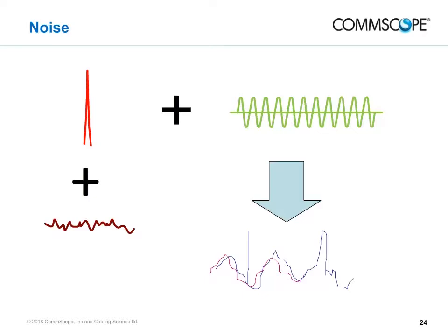Some is due to collisions and scattering that occur at the atomic level of conductors, as charges being transported encounter thermally excited electrons in the crystal lattice structure of the conductor. Another source of continuous noise is cosmic background radiation noise, which scientists attribute to the Big Bang that created our universe. Unlike valid signals, impulse and continuous noise are random.